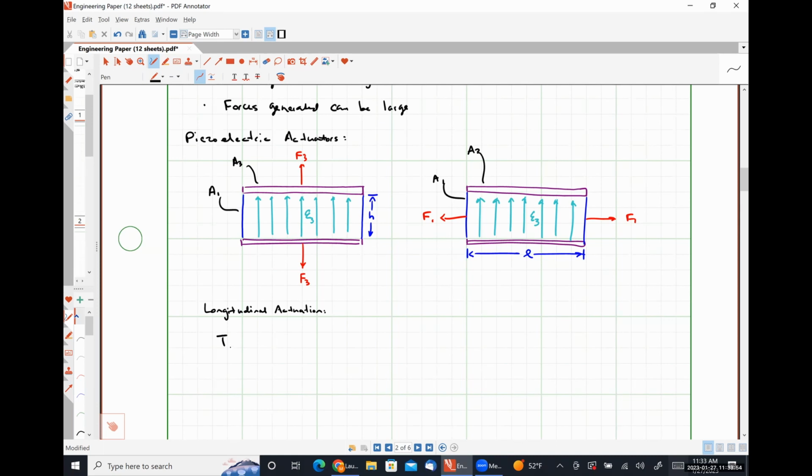So our constitutive equation that is going to relate our mechanical stress and our electrical stress is T3 will be equal to E times S3 minus lowercase e33 times fancy script E3. So many E's in this equation, it's ridiculous, okay? So effectively, stress is equal to mechanical strain minus electrical strain.